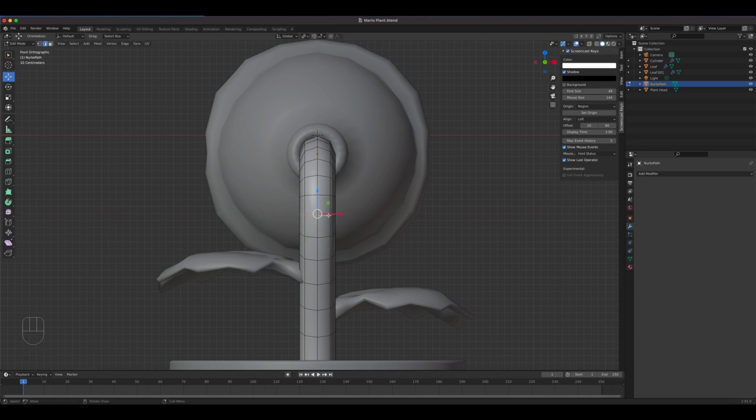So let's turn on a feature called proportional editing. When you turn this on, the keyboard shortcut is O. Sometimes you accidentally press this and it'll drive you nuts, because it has an area of influence and whatever's inside that reticle gets affected. So let me turn it on. Okay. And make sure you turn that off when you're done working.